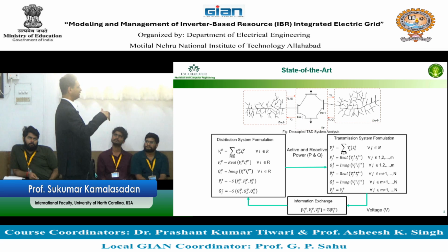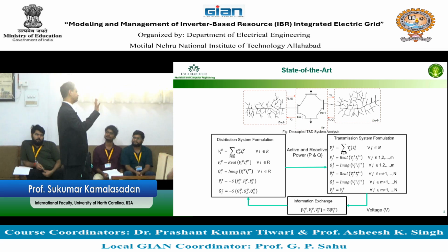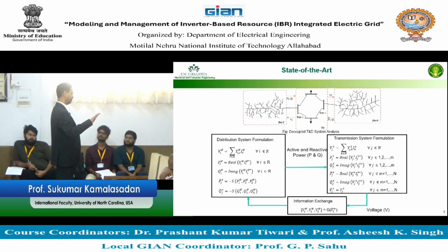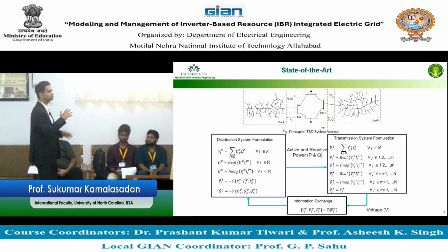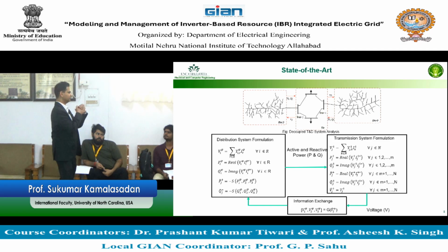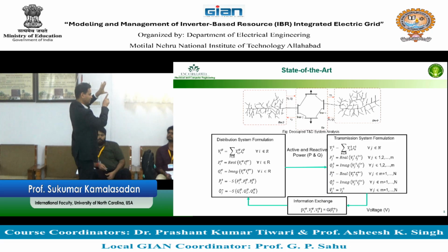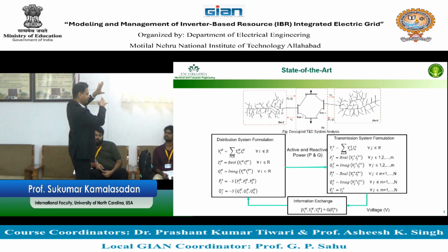If they won't come to exactly the same value, you will get a transmission system power flow for another value, which is also okay. But so that's a very good question. You have a transmission network and you are modeling the transmission network for power flow considering some spot load, right? If that spot load is different, then you are solving the power flow for another condition, not the same condition. Now, normally people don't solve the power flow with different spot load conditions.